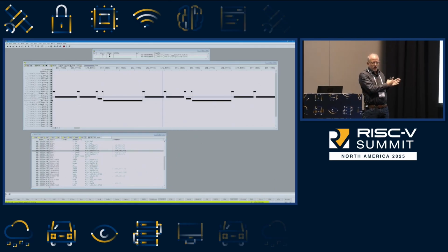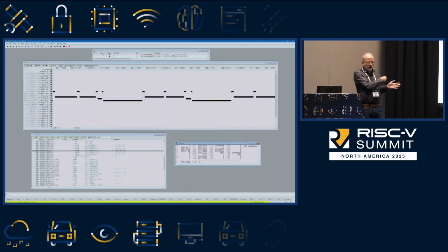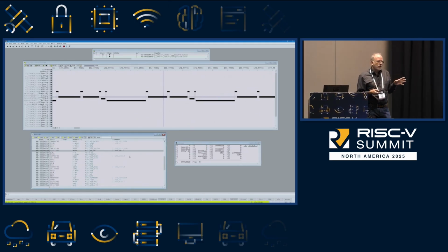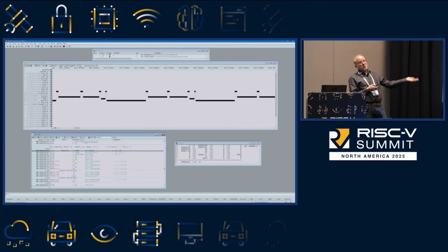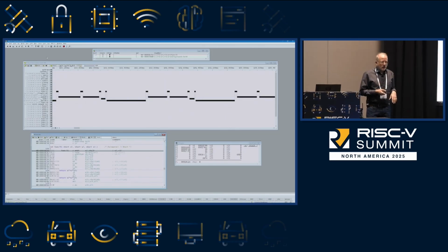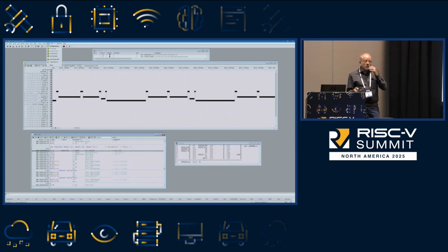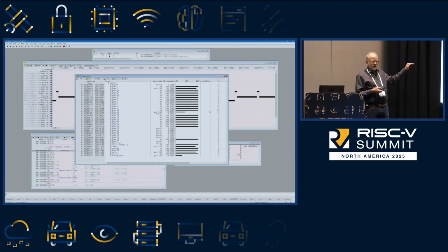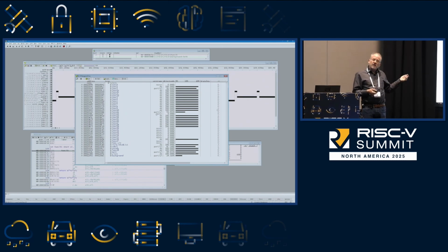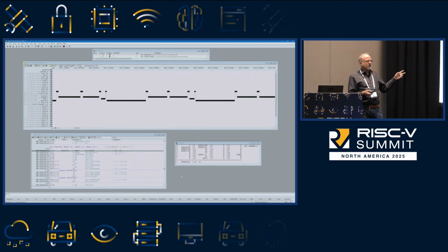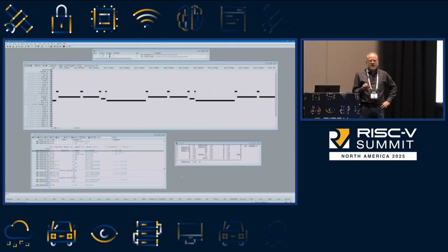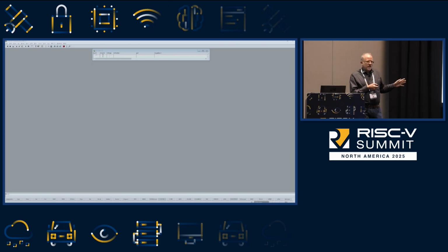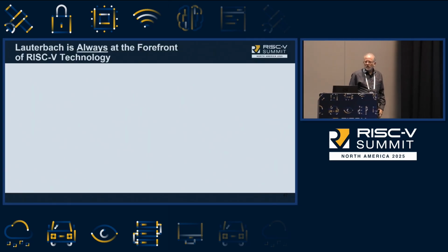Remember I said it's like a recording? So he's going to go backwards in time. And it gets very interesting because we can look at that and tell what the register values are going to be. So you can look at your registers and go back in time and see what that's like. And when you're done with that, then you can start doing the code coverage. That's going to show up in these bars. The thing to see here is that some of those bars are 100%, and there are some that are not quite 100%, and one that was not there at all. That meant that your testing wasn't very complete. So those are some of the things that you can do with Trace.